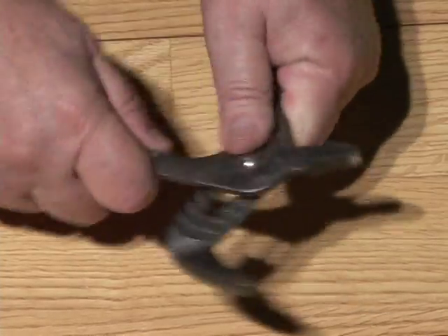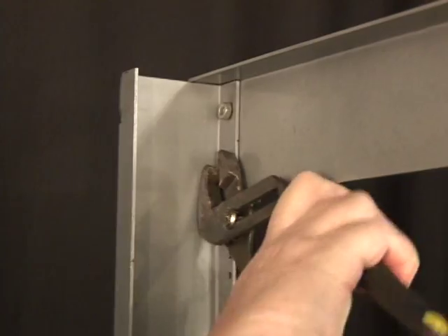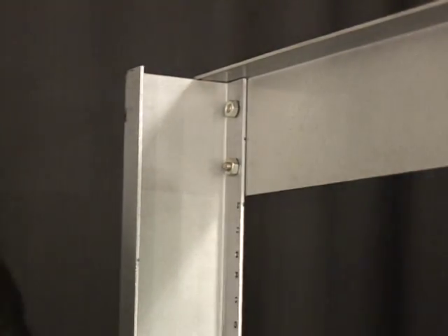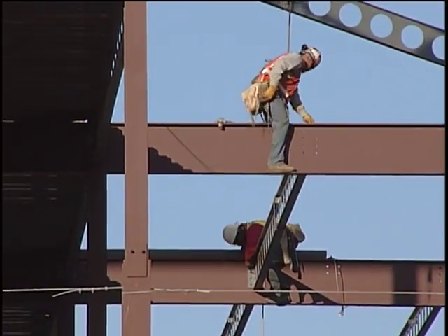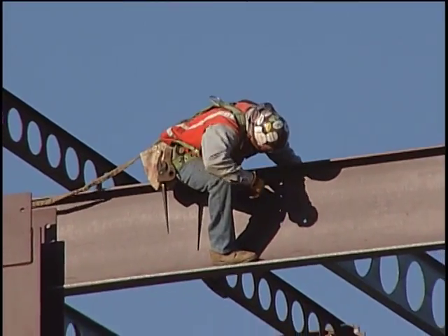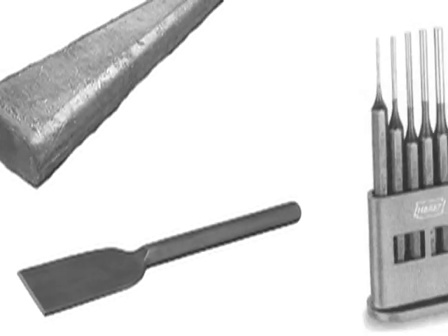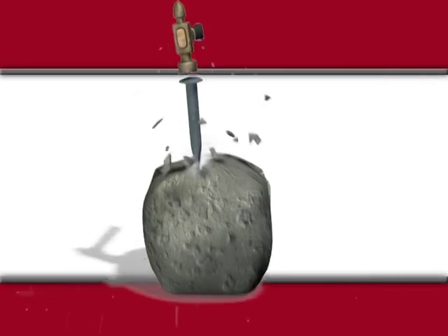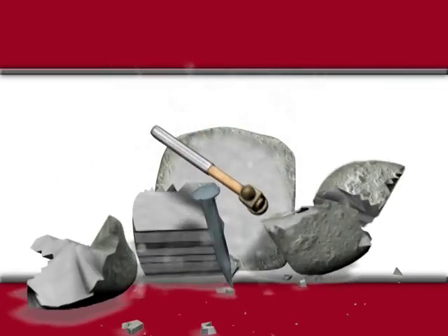Never use a wrench that has weakened or sprung jaws from being used improperly. The wrench can slip off the bolt or nut and cause you to scrape your hand and knuckles, cause you to fall from an elevated worksite, or fly out of your hands and hit someone or something. Never use a chipping tool such as a chisel or wedge that has a mushroomed head. This is a condition where the head of the tool is flared out due to excessive use. Use can cause pieces of the head to break off and hit the user or others.